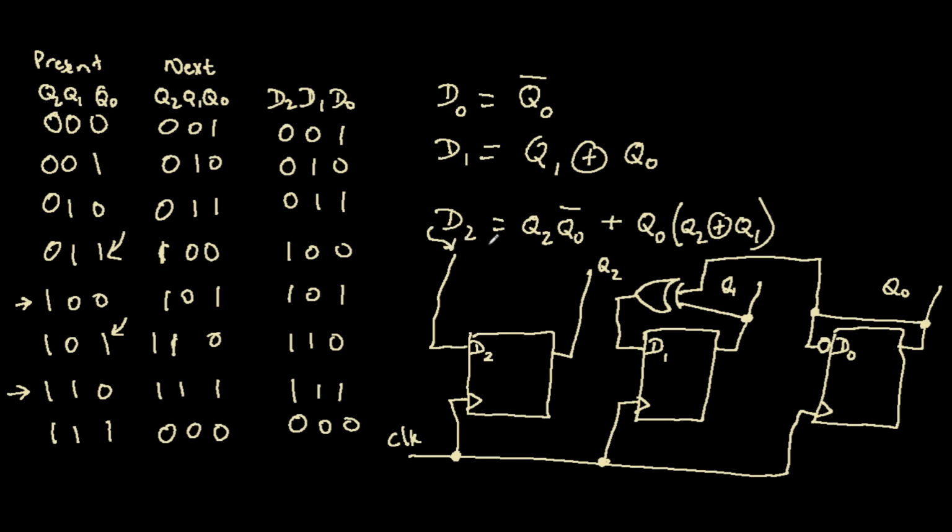So this is what you're supposed to connect into your D2, and your circuitry is done. Once we have this, it should work correctly. So let's go into VHDL. We'll write the code for this synchronous counter, and if we've done everything correctly, then when we simulate it in a test bench, we should see it counting through this sequence.